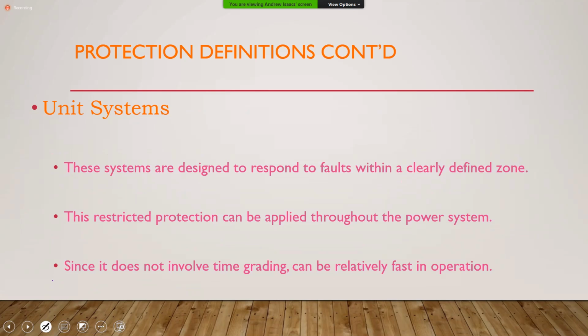So earlier we spoke about the type of protection systems or the methods of protection. Remember we talked about distance protection or differential protection. What we are saying here, like differential protection, it is looking at what's coming in and what's going out. If what is coming in is not equal to what is going out, and it passes a certain threshold, trip. So it doesn't ask any other question, it looks at what's coming in, it looks at what's going out.